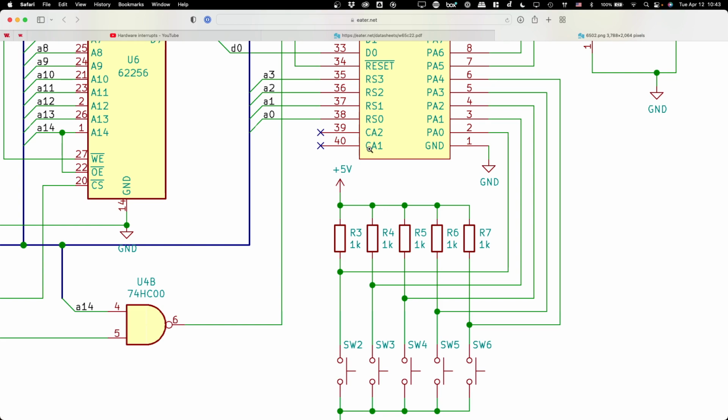No, if it's pressed, it'll be off because these are pull up resistors, not pull downs. And that's what this needs to do. Because if you make it an AND, if you press any of those, it's going to make a cascading false state, which will turn them all off. Yeah, exactly. So let's suppose that we are pressing none of them. Then what that means is all 5 of these data lines coming into PA0 through PA4 are logical 1s.